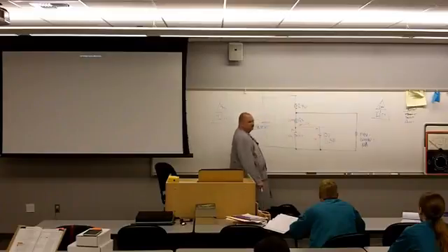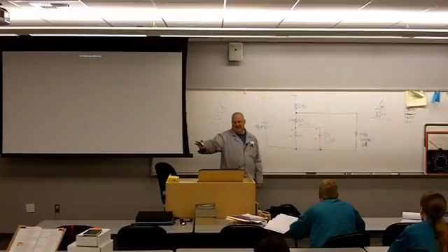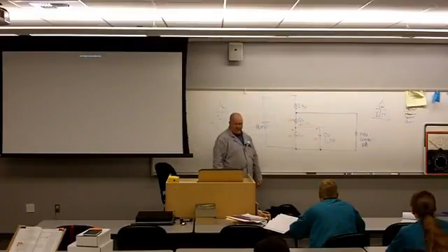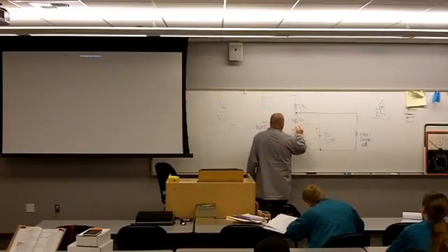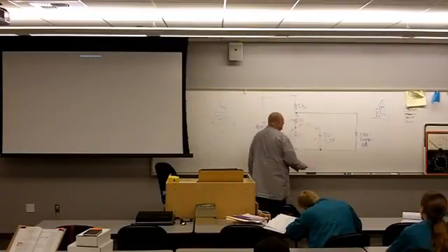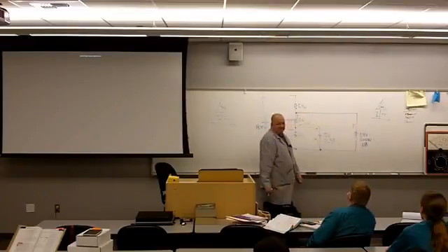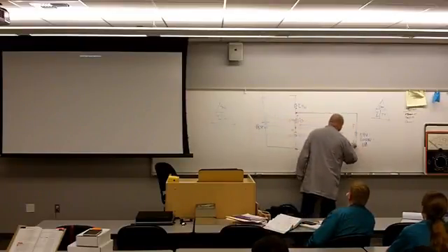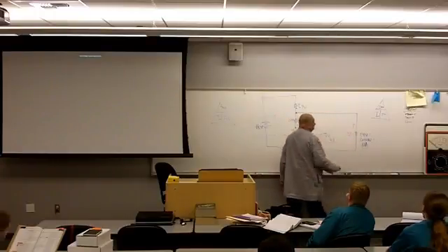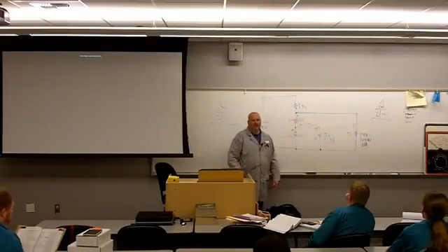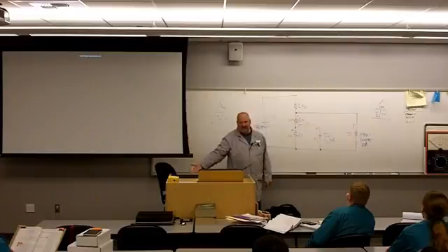1.55 amps. It's gotta work like this, if this thing's functioning. So I've got 1.55 amps coming up through here. Okay. How much current is coming up through this load? How do we know that? Placard data, technical documentation, calculation utilizing Watt's law.